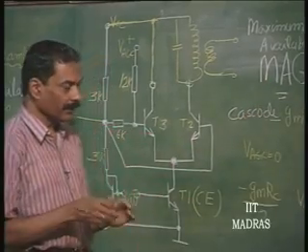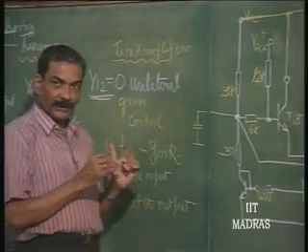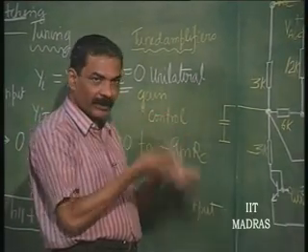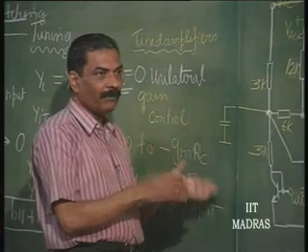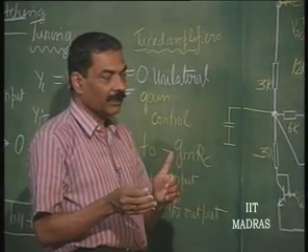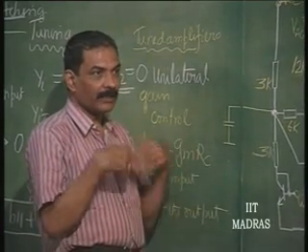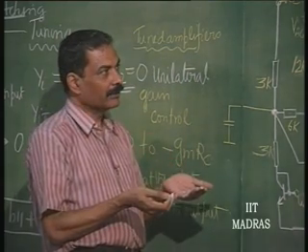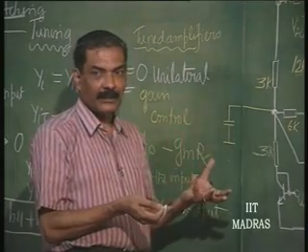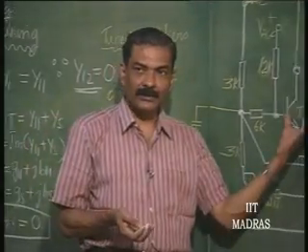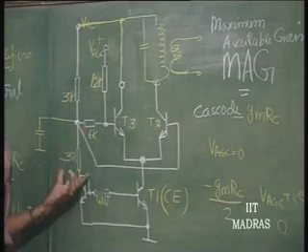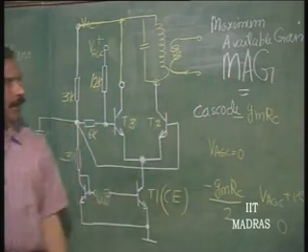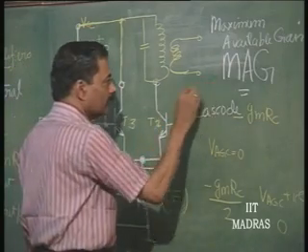What is the maximum available gain? Let us understand. The input is conjugate matched, so that the input source can deliver its maximum power to the input of the amplifier, then the amplifier amplifies with a certain power gain, and the output is delivered to the load by the amplifier when it is matched at the output also, conjugate match. Then whatever gain we get is characteristic of the amplifier that you are using, because you have optimized things at the input as well as the output, and that is called maximum available gain. Now, that is a power gain.